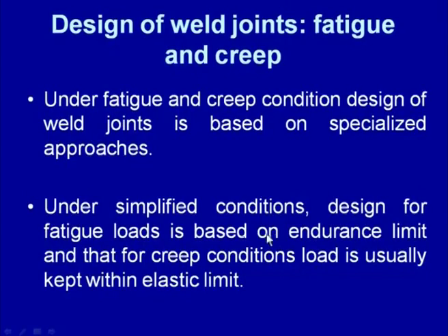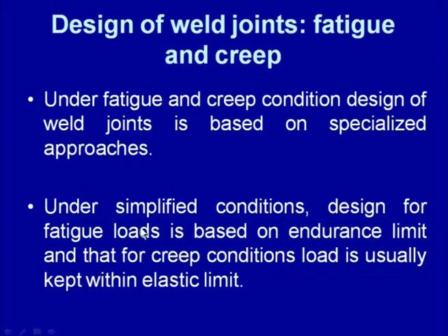We decide whether the weld joint will be designed on the basis of the endurance limit or in some other way. Under simplified conditions, design for the fatigue load is based on the endurance limit. So, this is the limit of the maximum stress or the stress amplitude below which there is no failure of the component under fatigue load conditions.